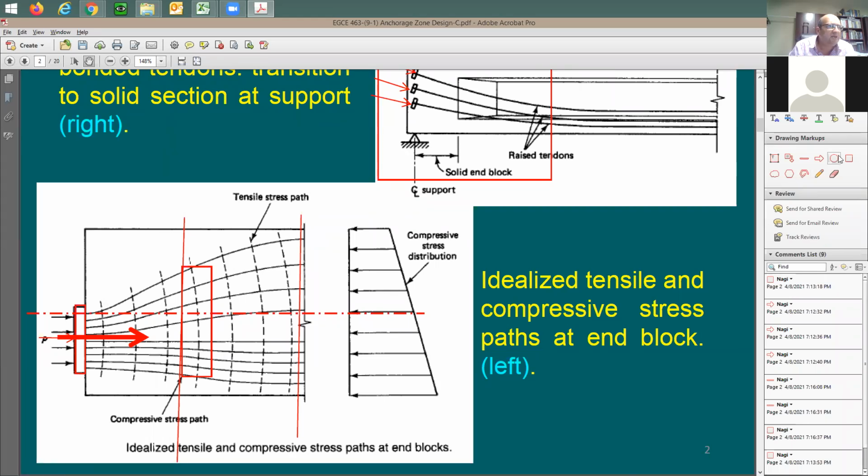If you change the section, if I decide here to take a section right here, the stress is going to be concentrated only on this location here. Let me draw this box. So in order for you to bring the stresses from being concentrated on one little section of the beam to the entire beam depth, it's going to take some distance. And this distance usually ranges from 1 times the depth to 2 times the depth. Most likely it's going to be equal to 2d.